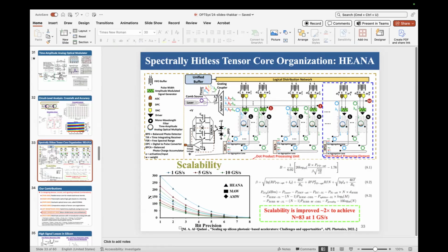And there is enough prior work. If you can control the noise, you can easily have thousands of these multiplication results, which are the pulse width amplitude modulation symbols. You can accumulate thousands of those before you reach the saturation of the TIA. So you can actually do in situ partial sum accumulation as well. That is the advantage of this as well.